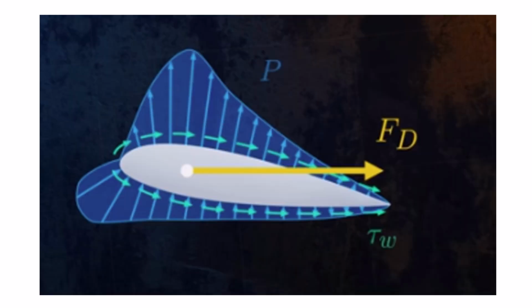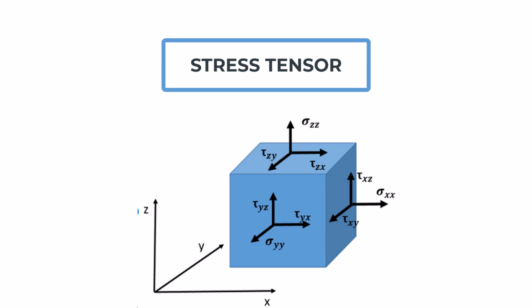The drag force is then the summation of these forces in the x direction. The lift force is the summation of these forces in the y direction. These are stored as stresses in what math heads call a stress tensor. They use this term to scare engineers and technicians even though it's just storing stresses in the x, y, and z directions.